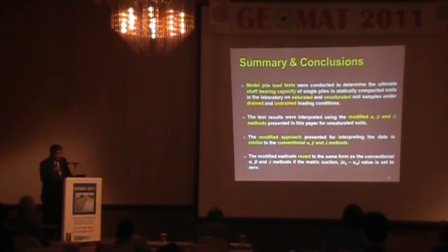The practicing engineer likes to use the same kind of approach that is already available to them, and we develop in such a way that there is a smooth transition from unsaturated condition to saturated condition. So that approach of alpha, beta and lambda has been modified, and we have tested for drained and undrained loading conditions and presented the approach.